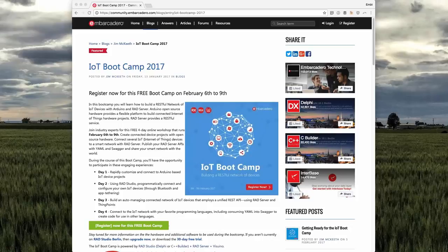Again, it's small, it's cheap, it has built-in Wi-Fi, and it has plenty of memory. The only disadvantage of Node MCU is that it has only one analog pin, and it's not that convenient to use as, let's say, the Arduino pins, but for everything else it's a fantastic board.